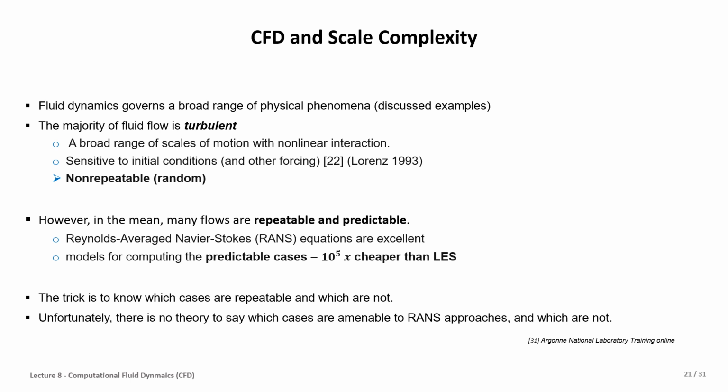And when we use RANS, LES, or DNS, we need to have the knowledge. However, because of the computation cost, DNS is so difficult to use, as it requires a lot of computation. LES and RANS have the most applications in research and in industry. However, industry prefers to use RANS. If there is an issue that cannot be covered by RANS, maybe they use LES.